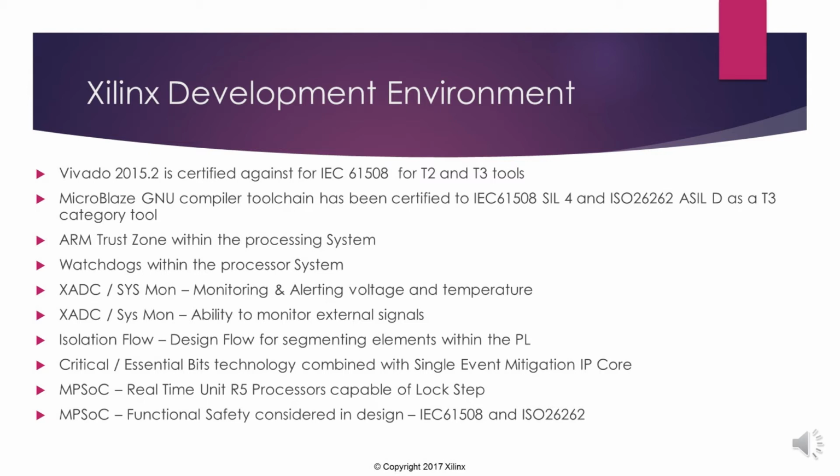Now, when it comes to configuration bits, sometimes there's concern over configuration bits being flipped and corrected. So we can use the essential bits technology and combine that with the single event mitigation IP core, which will look at it. And then if we're using the UltraScale Zynq, which is a really great device, there have even been devices added in there. So there are R5 real-time processors that are capable of running in lockstep, and the device itself has really been considered to create IEC 61508 and 26262 designs, to really simplify that further.